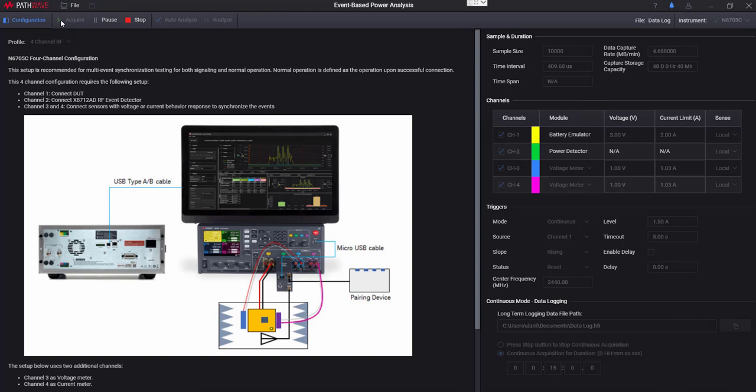Now, in the interest of time, I'm going to cut out most of the time, and I'll only show you what it looks like at the very end. We will be able to tell when the acquisition is done by the fact that the Acquire button turns into a bright green triangle again. Right now it's grayed out, indicating that the acquisition is still in progress. Okay, you can see that the Acquire button is now a bright green triangle, which indicates the acquisition is done.